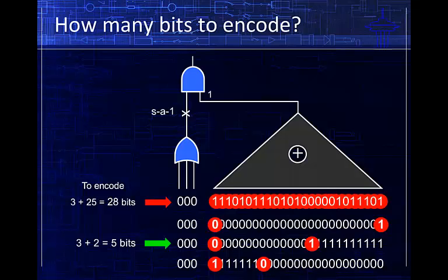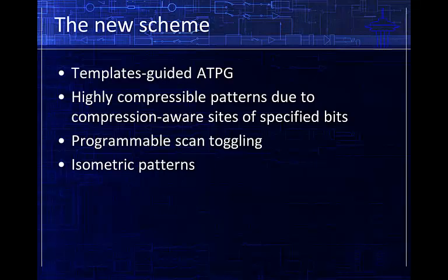So which one is easier to encode, or which one is easier to remember? My favorite is the second one. We start with 1, then we immediately toggle it to 0. It is not only easier to remember, but also easier to encode. In addition, the stimuli consumes much less power during shift. A single scan shift operation toggles 14 flip-flops in the first vector and only 1 in the second.